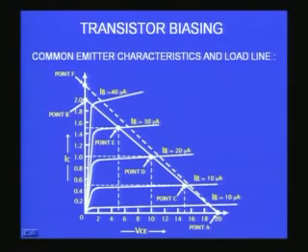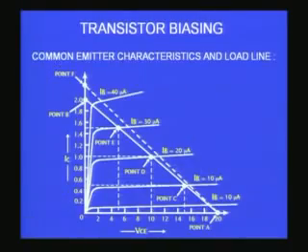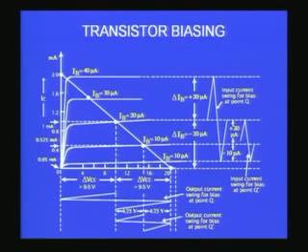So that load line will change whenever I change the load, which is the RC, or when I change the VCC. When I change the VCC also, it will go somewhere along this line, so it will be a new point, and when I change both, that also can lead to this type of a new load line. That is what I want to show you. Okay, now let us move on to the next point.